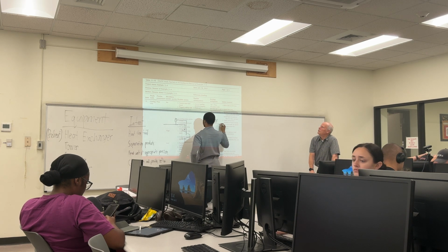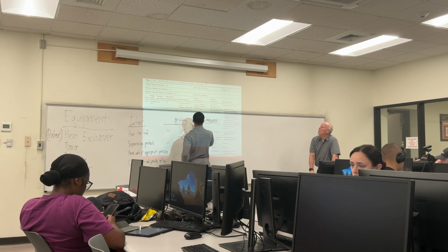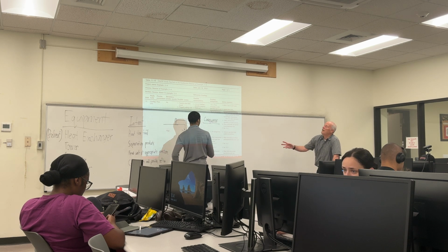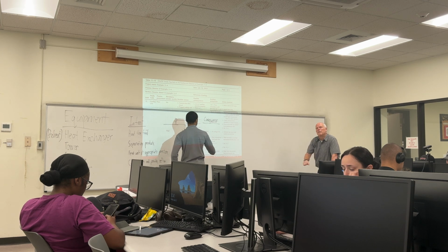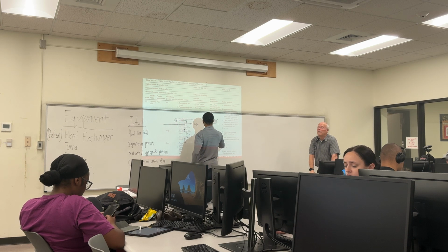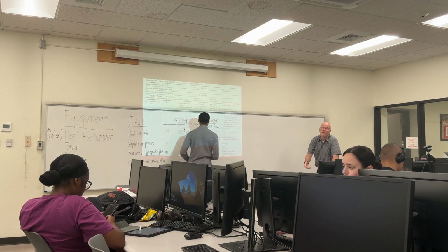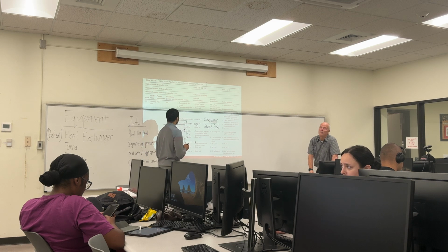First we say negation of its intention. So it doesn't work anymore. Then what's the consequence? Well, the consequence would be potential backflow, reverse flow for the unit. Now, I'll tell you, reverse flow to a unit is really scary to operators. So it probably ought to be scary to us too, but I guarantee you it's really scary for operators.